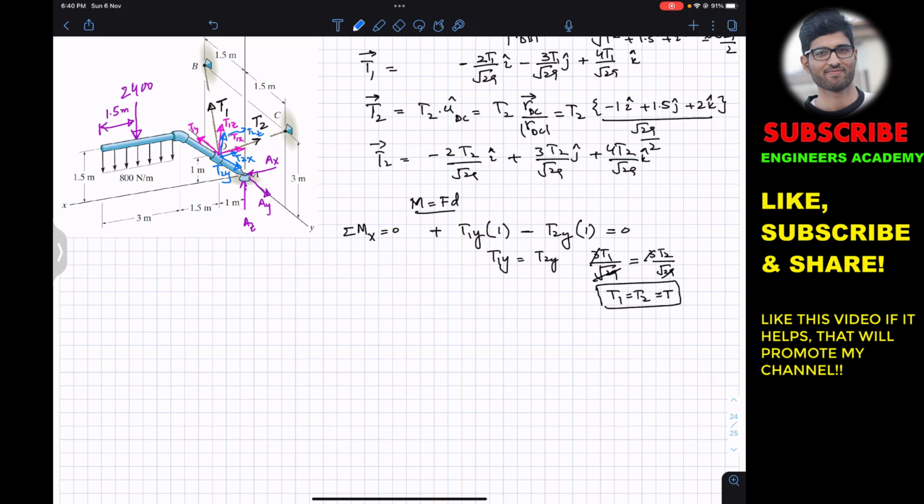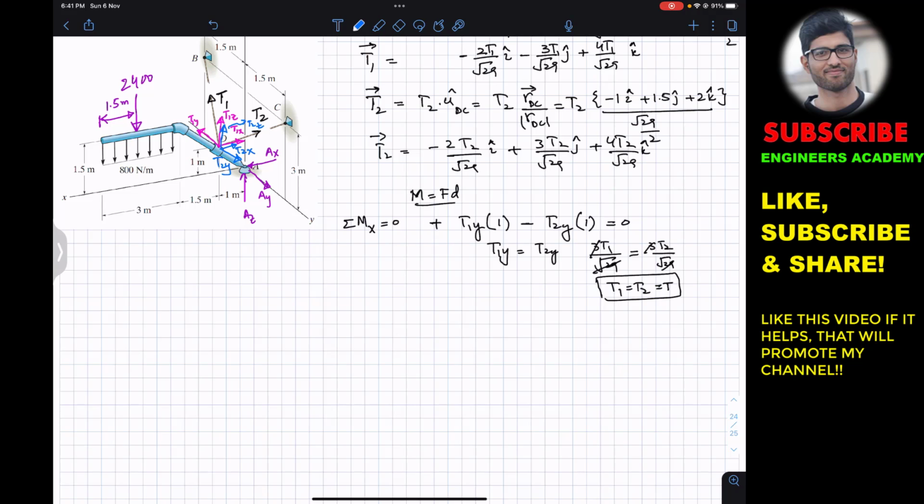Now after the summation of moment about the x-axis, we are going to apply the summation of moment about the y-axis, which will be equal to 0 as well. Again, Ay, Ax and Az are intersecting with the y-axis, so they will not come into our equation. Similarly, T1y and T2y are parallel with the y-axis, so they are not going to produce a moment about the y-axis. So these x components and z components are going to produce a moment about the y-axis, and this 2400 is also going to produce a moment about the y-axis.